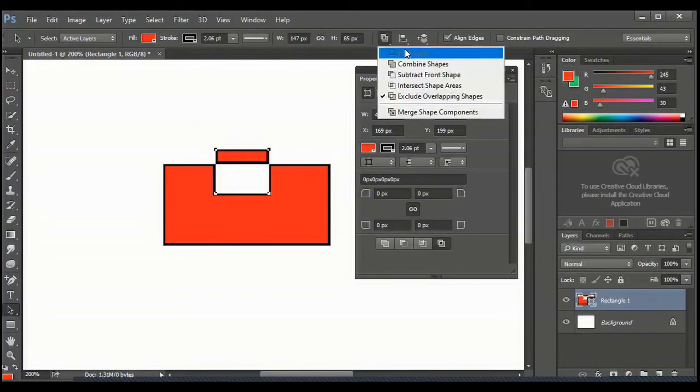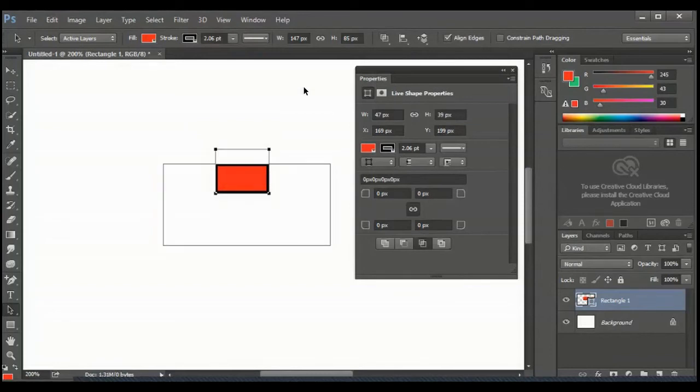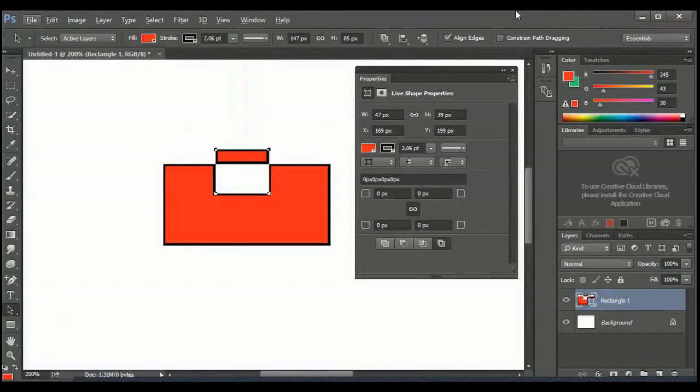New layer, usually the default will be new layer. If you want a combined layer, and if you want subtract, and sometimes you may require some shape where you want an inner circle, there you can use combine and then subtract and other things you can try. As I mentioned, it may require some memory, so you may have to be very careful when you use this command.